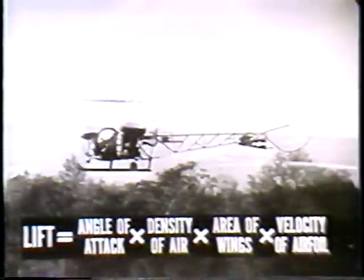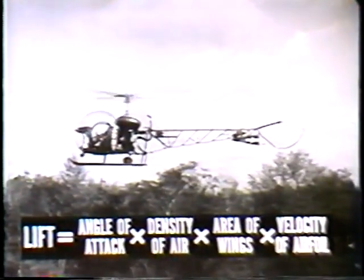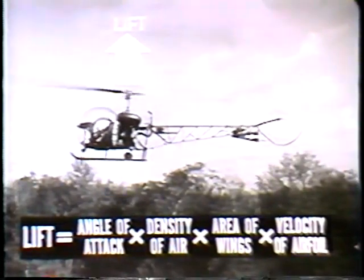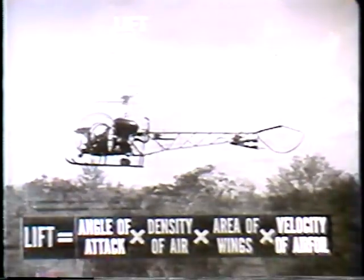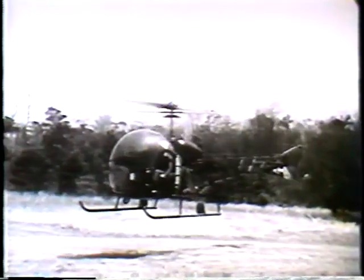Now let's review some of the more important points of this film. Of the four factors which give you lift, a helicopter pilot can control only two: the angle of attack and the velocity of the airfoil. Since rotor RPM is kept constant, the only way to vary lift is to vary angle of attack. Lift holds you up and also provides horizontal and vertical control.